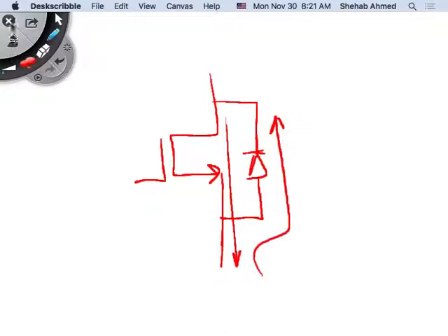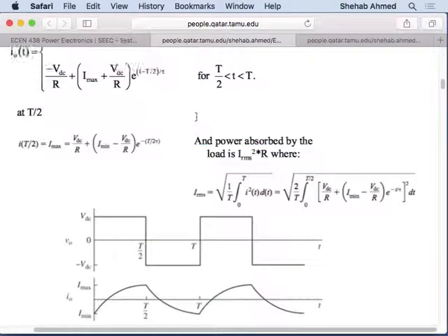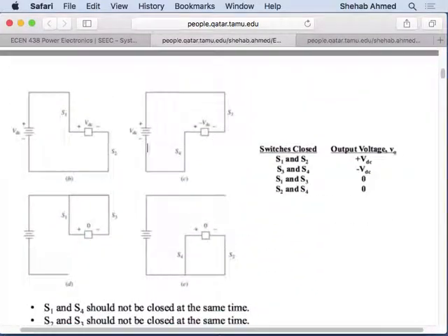So in an inverter application, this is the same switch, right? Here, as long as I have positive VDC, that means I have this switch and this switch on, S1 and S2 on, right? These are the only switches that are going to be on when the voltage is positive.